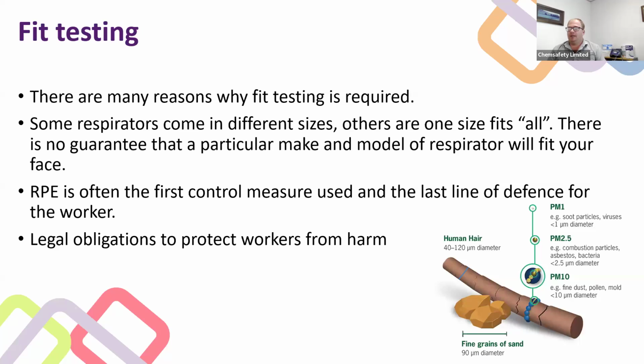So fit testing, there are lots of reasons why fit testing is required. Some respirators come in different sizes. So this one here is a small medium. You can get medium large and large, extra large. There's lots of different sizes, but there's no guarantee that even with those sizes, that particular respirator will fit your particular face shape.